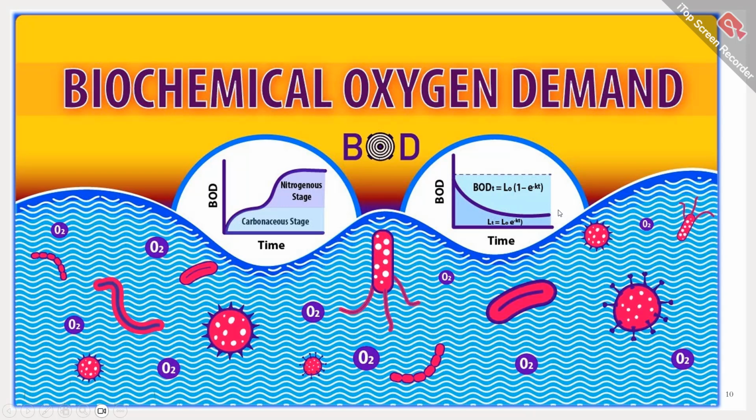Okay. So how do the microbes decrease the BOD of the water? BOD is nothing but the indirect measurement of the pollutants present inside the water, that is, of the biodegradable pollutants. So they are aerobic bacteria or aerobic microbes. They use the dissolved oxygen that is there inside the water.